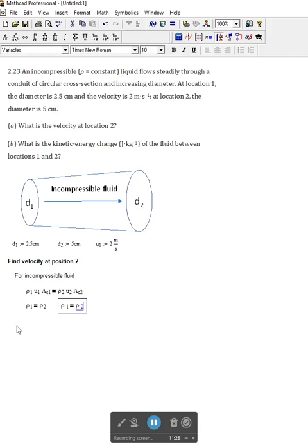All right. And once that is entered, I encourage you when you're using MathCad to put steps of your derivations in place so that you can follow your solution, especially if you make mistakes. So now our formula is u dot 1 times A dot c1, and I'm going to keep this symbolic equal sign, Control Enter, u dot 2 times, and the multiplication is just your asterisk, so Shift 8, times A dot c2. All right.